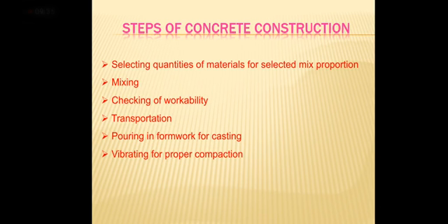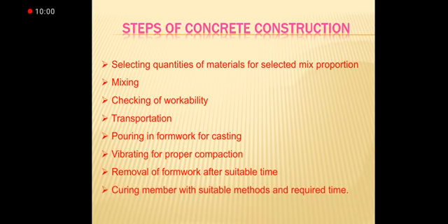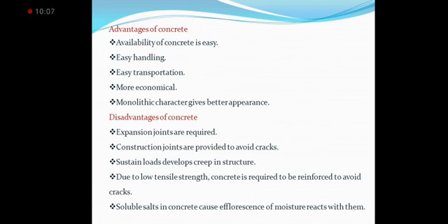When we pour the concrete, it is not set properly. We need to provide some compaction, vibration. So we will be using some vibration, or we have some other methods for the compaction. The concrete poured in the framework should be properly settled. It means the voids should be removed. Then after it sets properly, the next day or very next day we can remove the formwork. Then the curing process will start. The curing process is very important to gain the strength. As we do curing, the strength will improve.